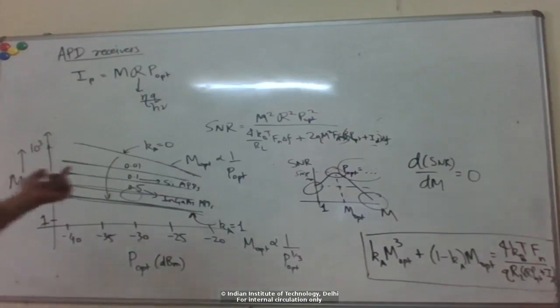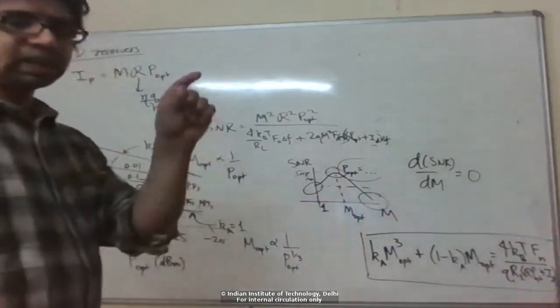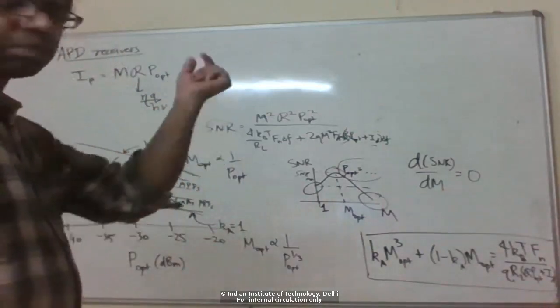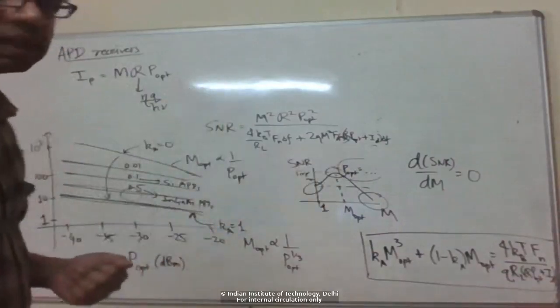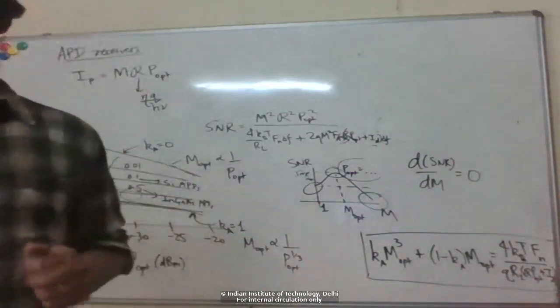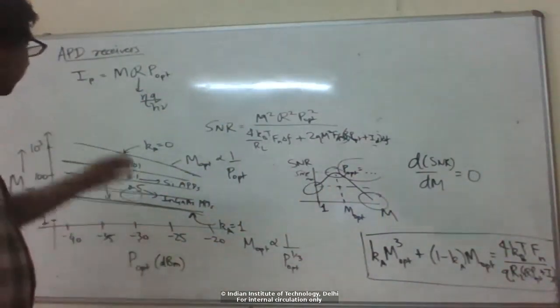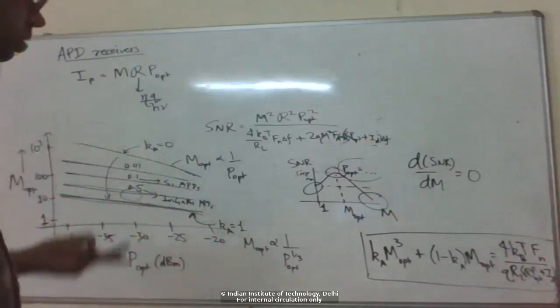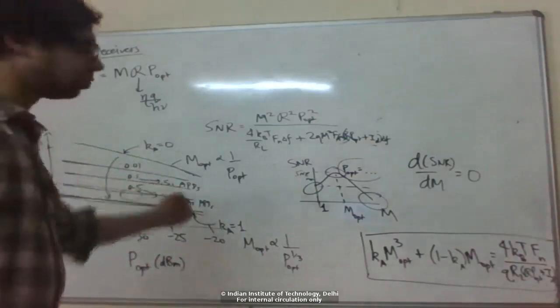Basically we saw that in terms of the device design, the way to control this M is by the thickness of that extra P layer that we add, which acts as the avalanche multiplication layer. By controlling that thickness, you can control this M, because all other factors like Ka and the electron and hole impact ionization factors are constant once you choose your material.